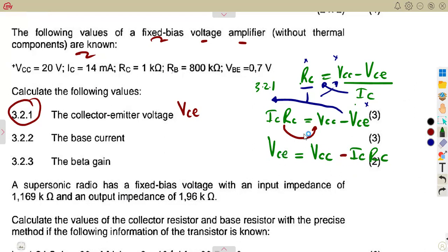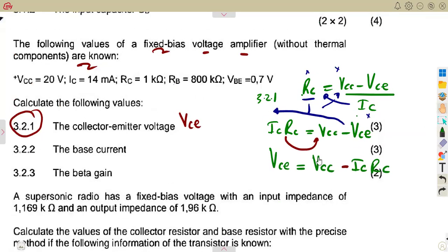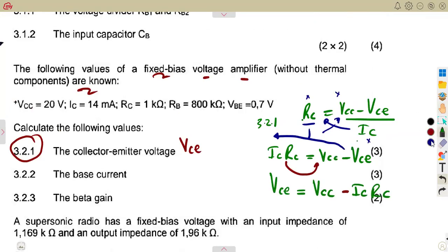Also, guys, in these transistor amplifiers you need to understand that the VCE you're calculating is a voltage drop across the collector emitter. It is taken from VCC, so it cannot add here. It was just a mistake in our formula sheet, in our memo.